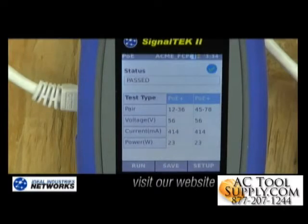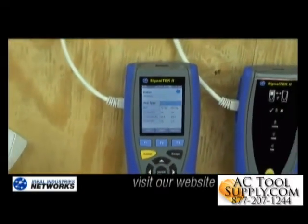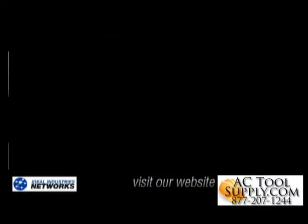Now, I'll run a load test, and you can see that the PoE injector I'm connected to actually shows me what pairs PoE is available on, and the voltage level, the current in milliamps, and how many watts are available. Now, I can test at the end of a long cable to make sure enough power is getting to my PoE device that I need to power.